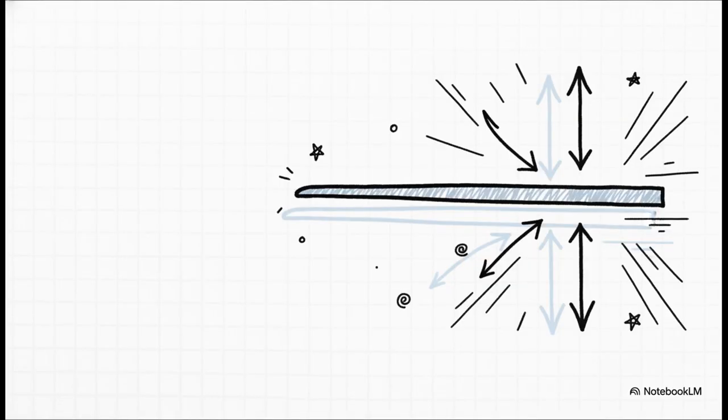Let's look closely at what actually survives our zero filter for the cantilever beam. We are left with displacement 2, slope 2, displacement 3, and slope 3. Basically, these are the free-moving parts of our diving board. These leftover variables represent the specific, unknown physical movements we still need to solve for, and our primary equation is now perfectly sized to do exactly that.